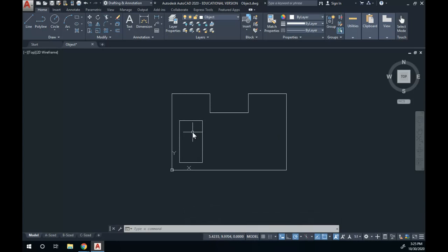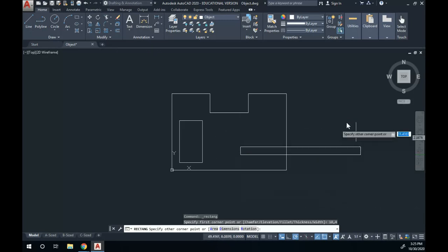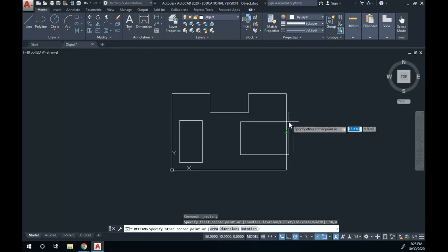Draw a second rectangle with the first corner at point 18, comma 4, and the dimensions shown in figure 2-27. So I'm going to go to the rectangle command again, and I want to type in 18. I'm going to hit the tab key, 4, enter. It locks me in. And it says that it should be 5 units up and 8 units to the right.